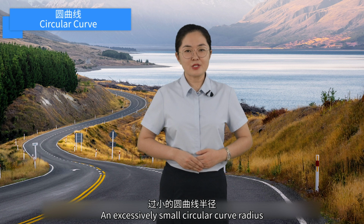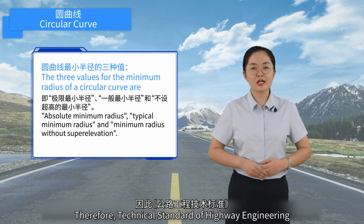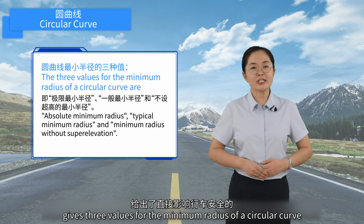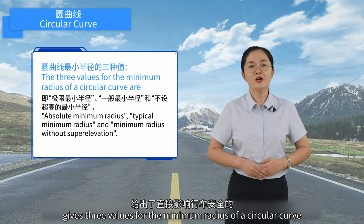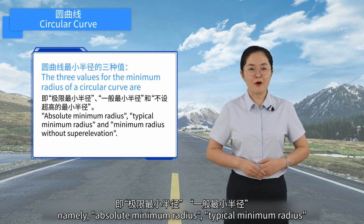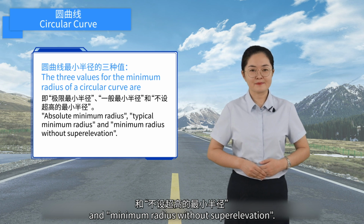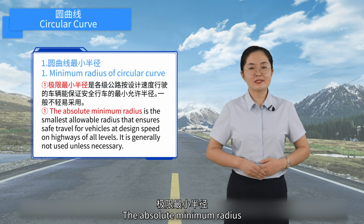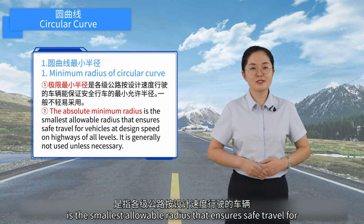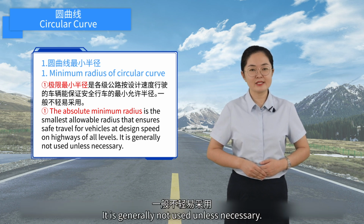An excessively small circular curve radius cannot ensure the safety and comfort of vehicles turning. Therefore, Technical Standard of Highway Engineering gives three values of the minimum radius of circular curve that directly impacts driving safety, namely absolute minimum radius, typical minimum radius, and minimum radius without superelevation. The absolute minimum radius is the smallest allowable radius that ensures safe travel for vehicles at design speed on highways of all levels. It is generally not used unless necessary.